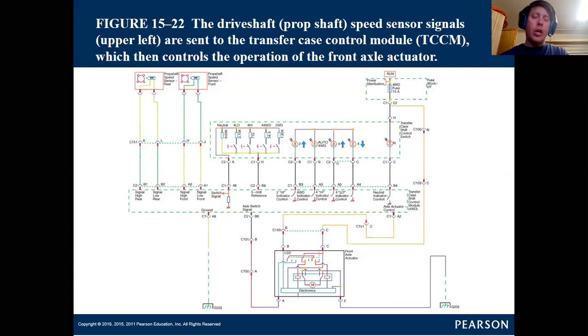If you're looking at the electronically controlled, computer controlled cars and trucks that are 4-wheel drive, it goes from switch to module and then to encoder motor. And it could go from switch to body control module to transfer case control module. There could be extra modules in place. But long story short, if it's got a computer, it's going to have data lines of some kind.